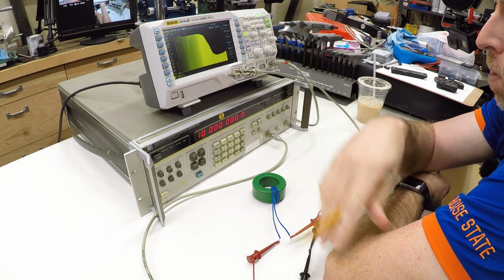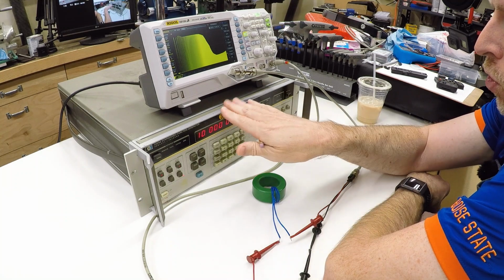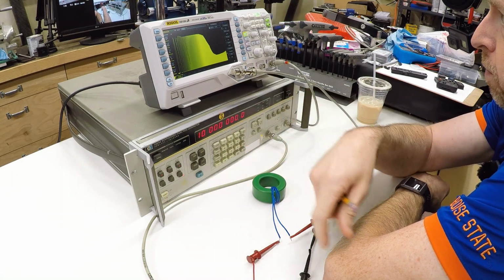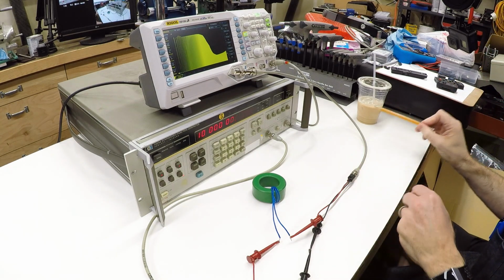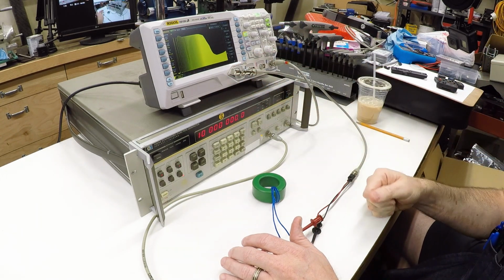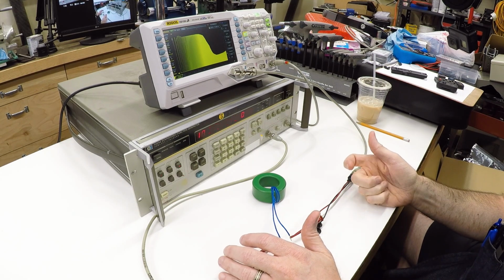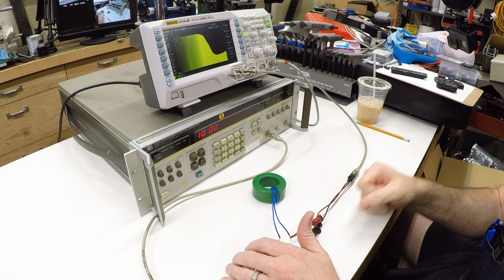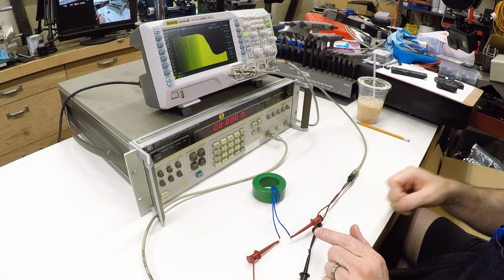And we can get a frequency response plot here by adding a function generator. These function generators, I mean, this is old tech, but these are available on eBay, not too expensive. And so this is a relatively inexpensive setup to be able to do this compared to a proper sweep generator or a spectrum analyzer.